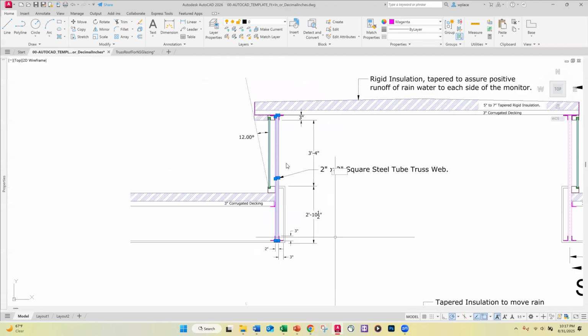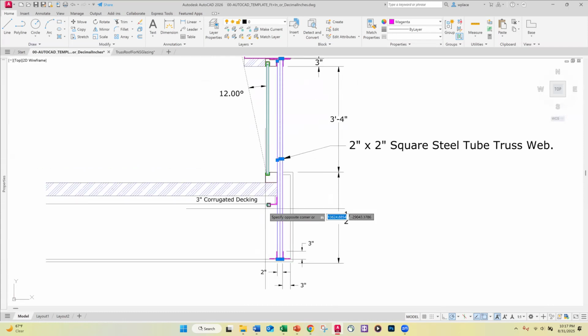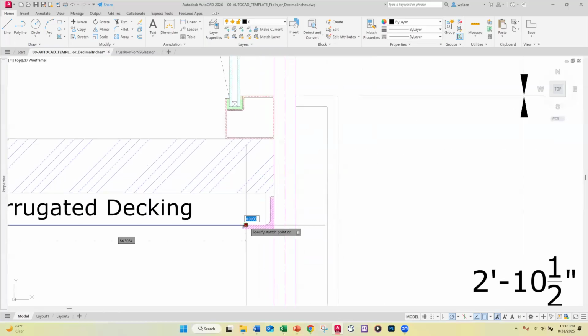I'm not only a little concerned about those things buckling, but you'll also notice that I'm attaching some angles that are going to get welded or connected in some way to these web members. And then I'm going to have this 3-inch decking resting on that. And the way these lines are stopping short is a little confusing to you.